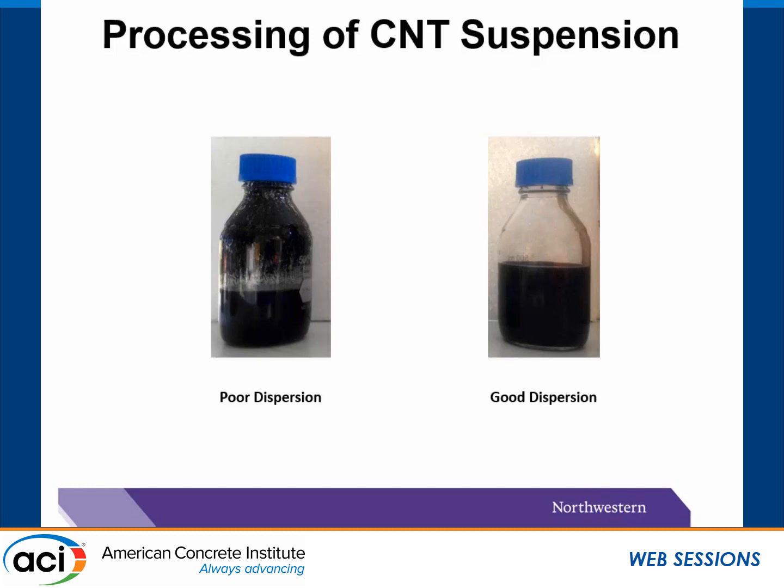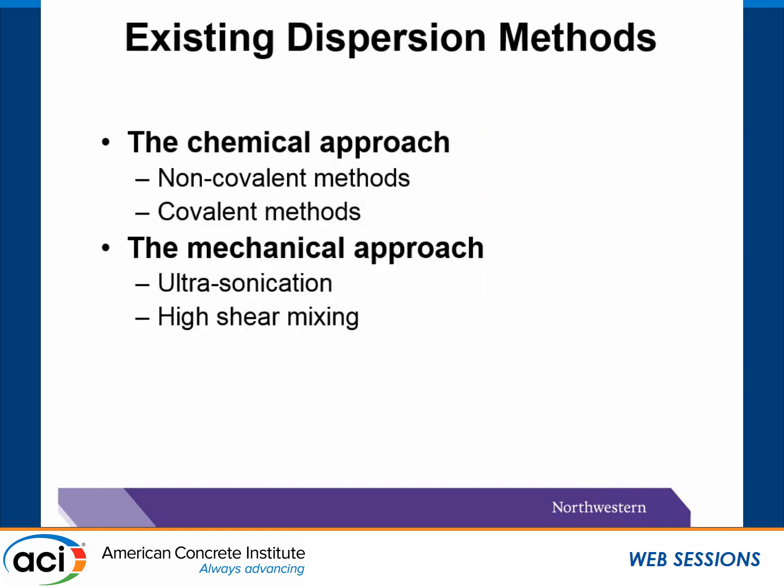The poor dispersion and rope-like entanglement of CNT in the composite matrix always lead to many defects in the composite and limit the efficiency of the use of CNT materials. A proper agitation must be used to break the CNT agglomeration. The picture here is showing a bad agglomeration, a bad dispersion in aqueous solution.